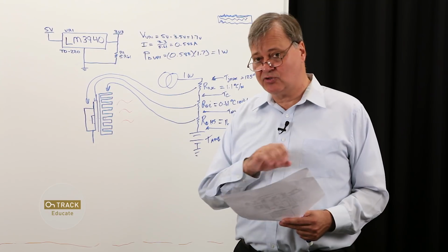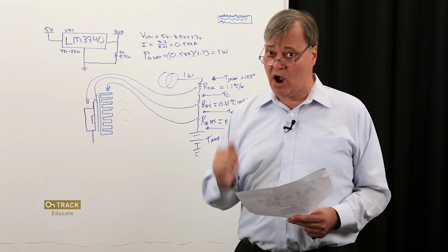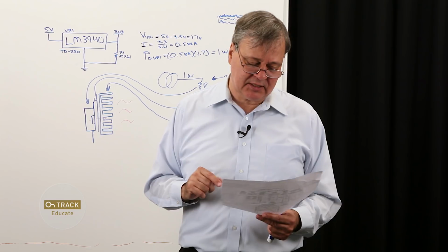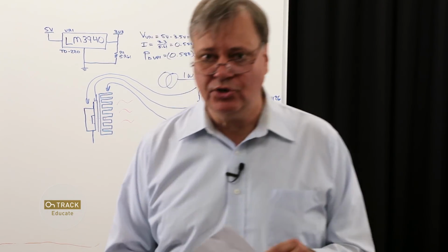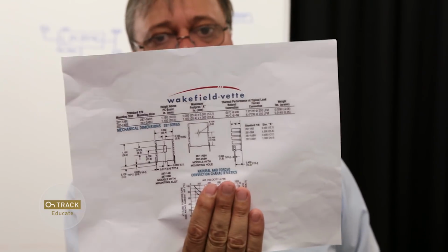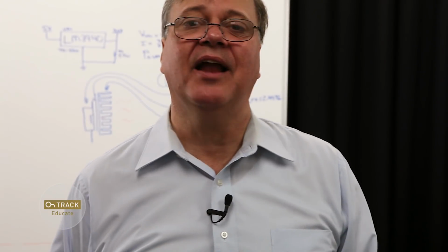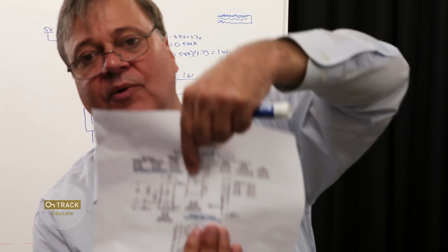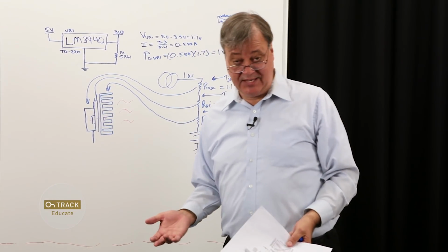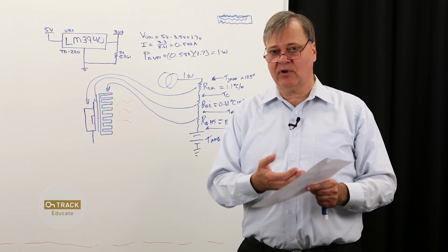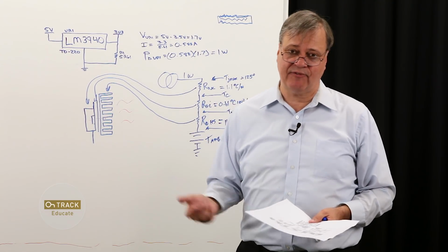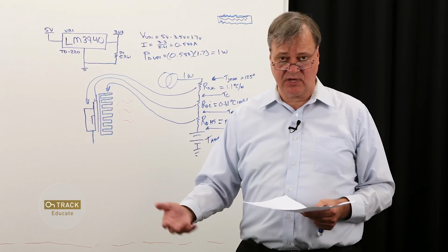However, when you're sizing a heatsink, you do need to stare at this graph a little bit and figure out what your operating point is. Now, the other thing that is important to know here is that these numbers assume that the heat is being distributed into this entire heat sink uniformly over its surface, which is simply not the case. Our TO220 package is mounted right in the center of this surface. So our TO220 package actually looks like a point heat source. And we have to account for the heat spreading throughout the body of this thermal conductor. This is actually referred to as the spreading resistance of the heatsink.